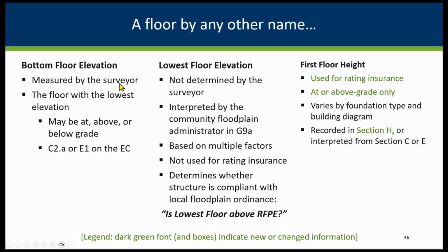And that's what's measured by the surveyor, and it can be at, above, or below grade. That is the bottom floor. The lowest floor elevation is determined for regulatory purposes. So that's not measured by the surveyor. It's interpreted based on the information in that section. And that's what determines whether the structure is compliant with that local ordinance.